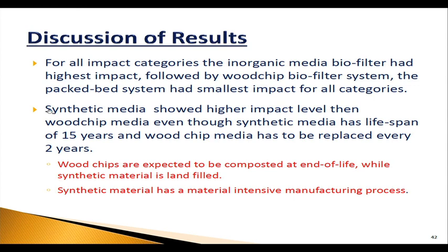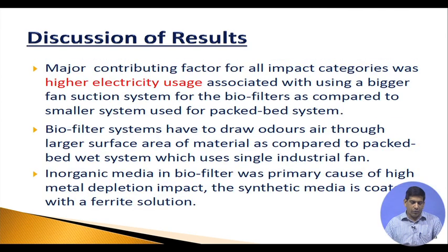The packed bed system had the smallest impact of all categories. Synthetic media showed higher impact level than wood chip media, even though synthetic media has a lifespan of 15 years and wood chip media had to be replaced every 2 years. Wood chips are expected to be composted at the end of life. Again, that's what has been assumed, while the synthetic media will go to landfill. Synthetic material has a material intensive manufacturing process, so that also leads to a problem.